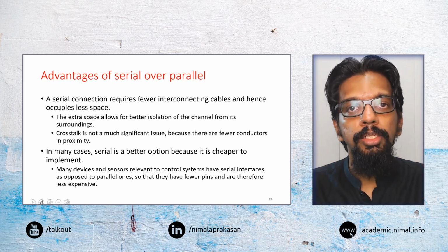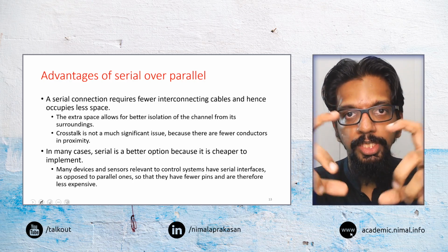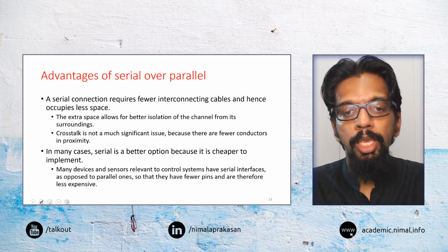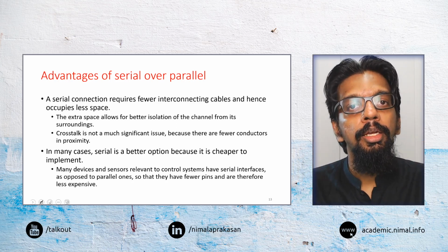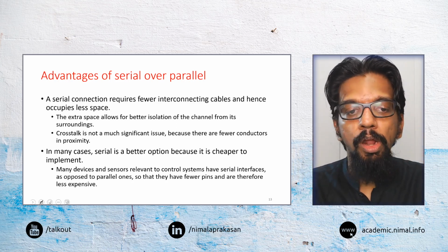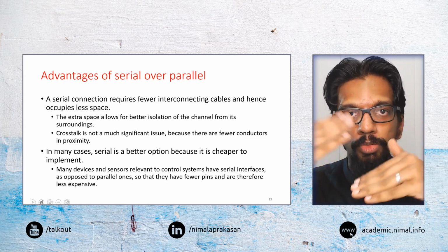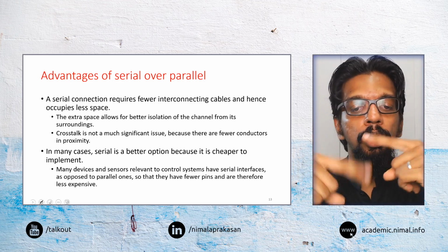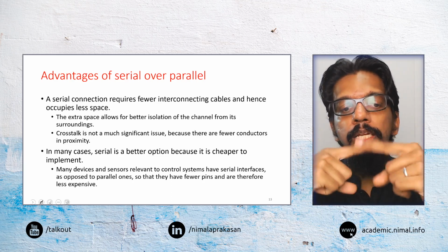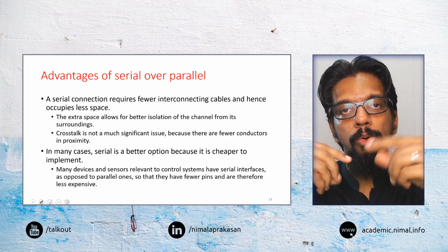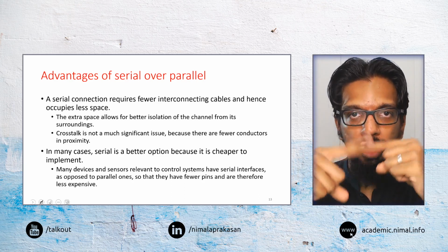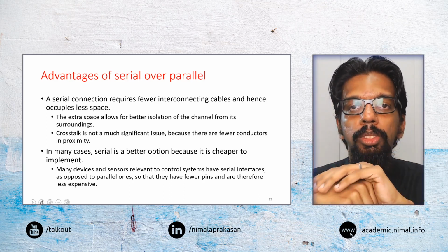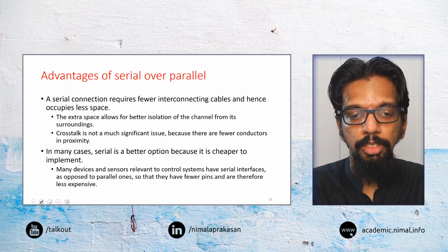So it requires less space to physically locate them in terms of the ports or cables and so on. And because we don't have a lot of wires or cables, there's no issue in terms of signal interference, crosstalk and so on, because of cables having magnetic interference. So that is also not there in serial communication.